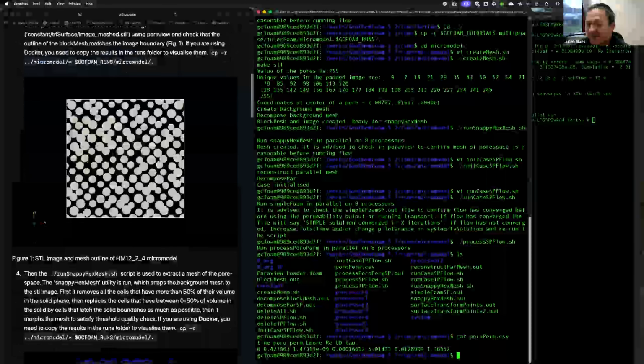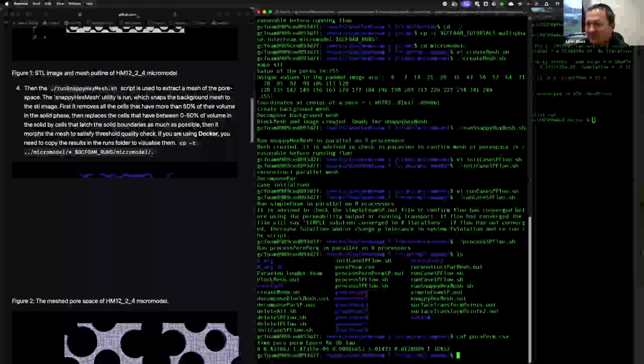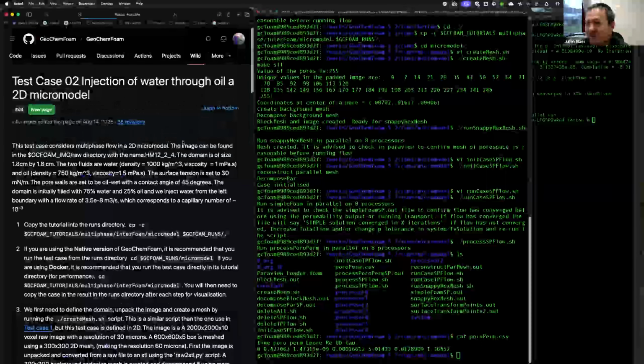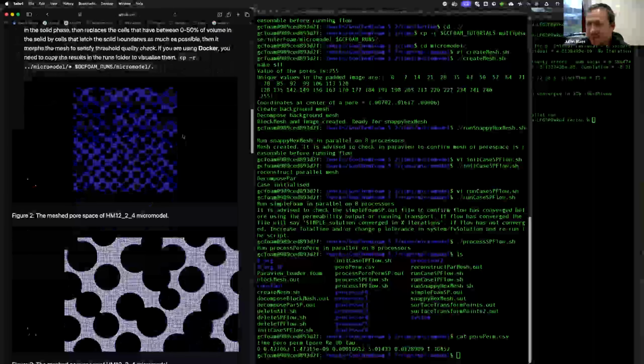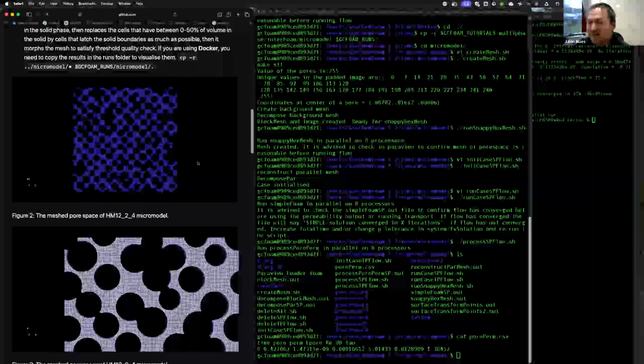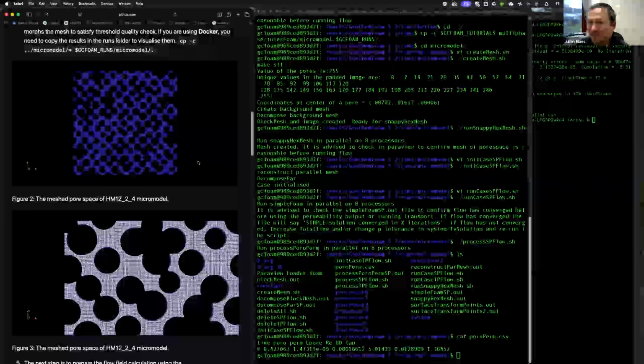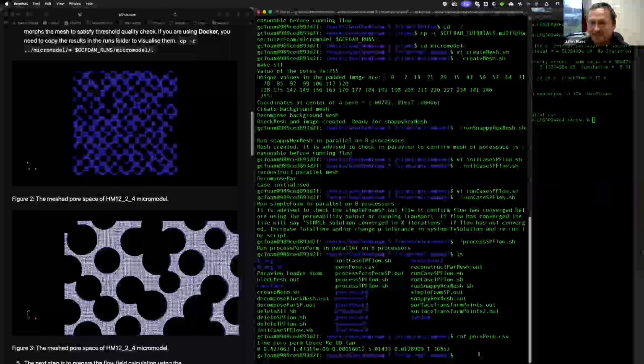If we're interested in permeability, we'll do it at a much lower flow rate. We will rerun this with a lower flow rate. The problem is we want this to be fast, and multi-phase flow takes a long time. So ignore the fact that the results are not quite right here, so that we can just run this in 5 minutes rather than in a few hours, right? If you want to do this properly, divide the flow rate by 100. We have committed such crimes before.